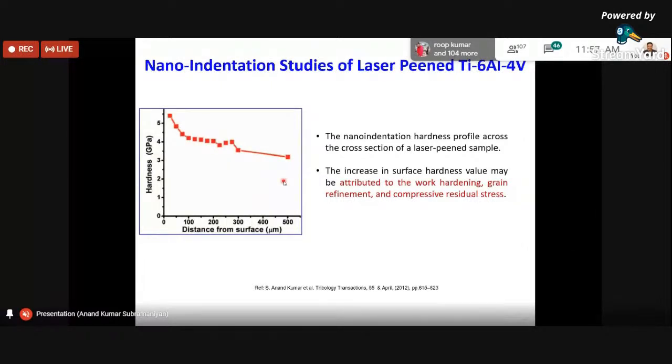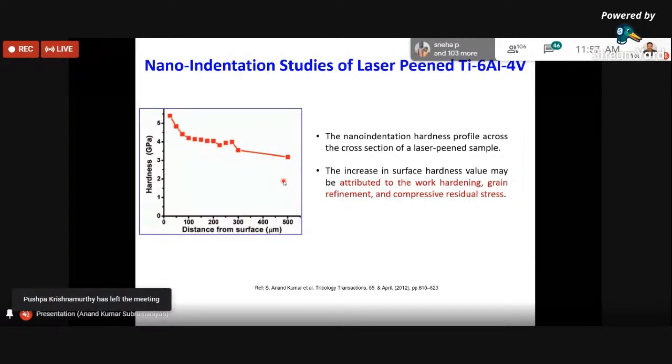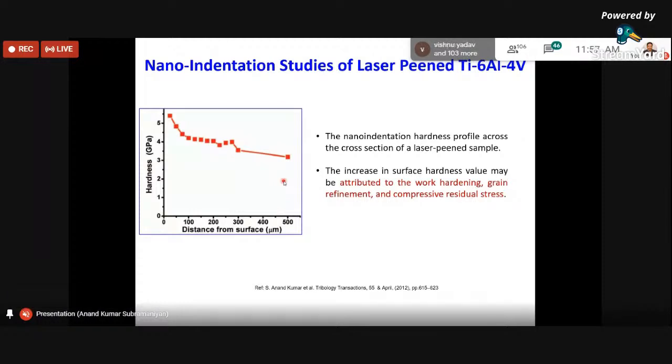So, if not from contamination from the ball, because of the slight increase in temperature during this process, there is going to be some amount of oxidation or oxide layer forming on the substrate. So one has to look into that also. The chemical reaction and contamination can enter not only from the ball material. We need to take care of temperature also.